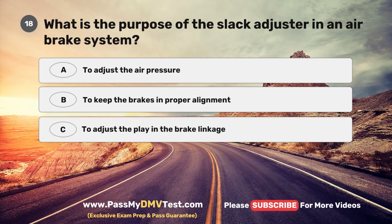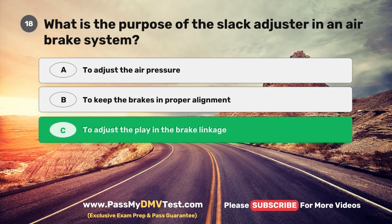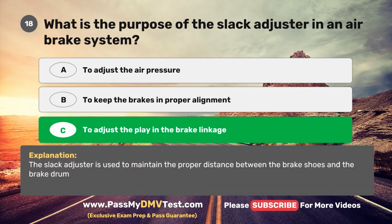Question 18. What is the purpose of the slack adjuster in an air brake system? A. To adjust the air pressure. B. To keep the brakes in proper alignment. C. To adjust the play in the brake linkage. The correct answer is C. To adjust the play in the brake linkage. The slack adjuster is used to maintain the proper distance between the brake shoes and the brake drum.